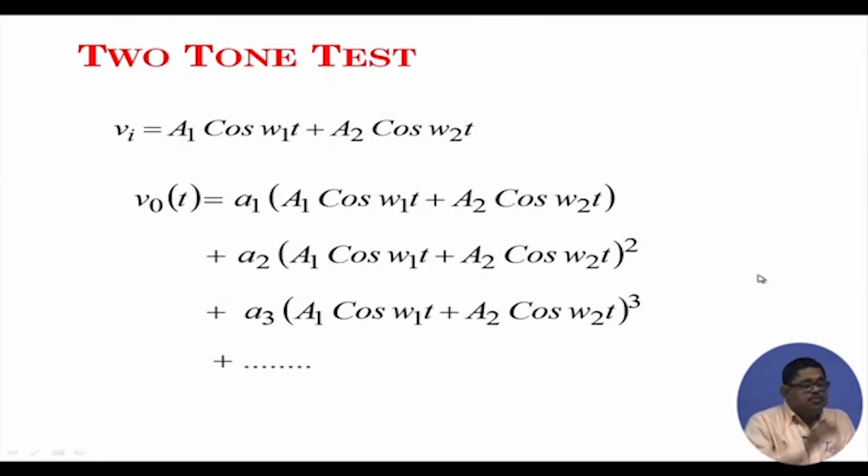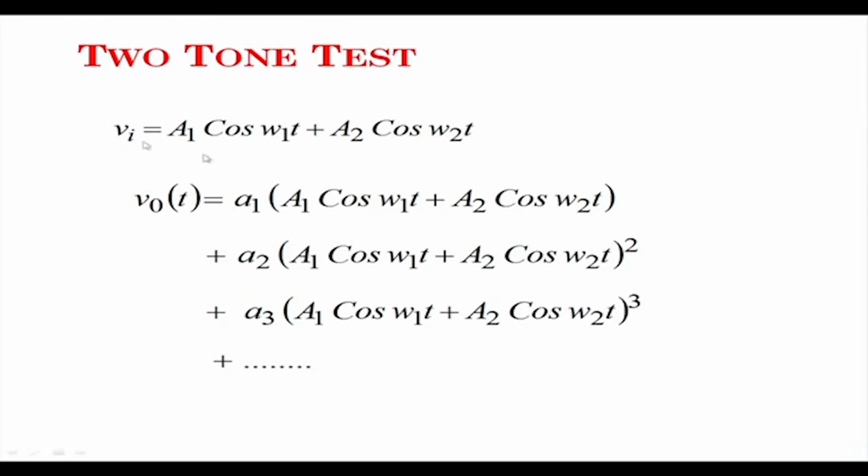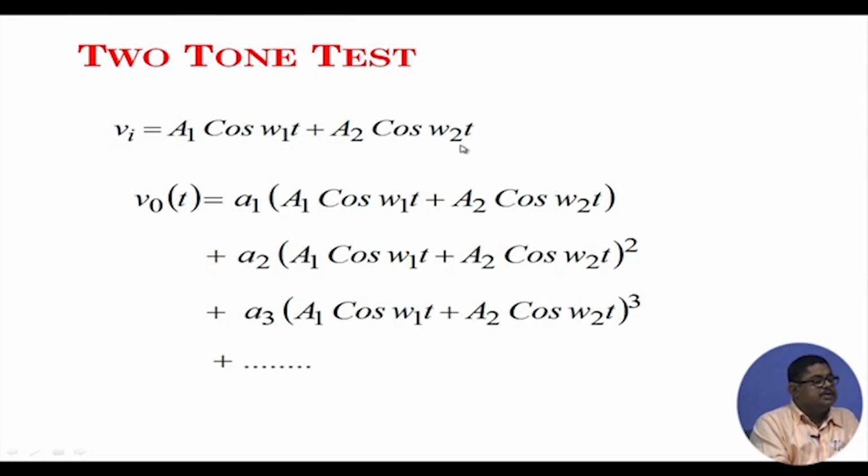So, to see how much nonlinearity we have, let us consider a two tone test. What is a two tone test? Though we have many frequencies, let us assume that we have two frequencies, omega 1 and omega 2 angular frequencies, correspondingly f 1 and f 2. So, in my input signal I have capital A 1